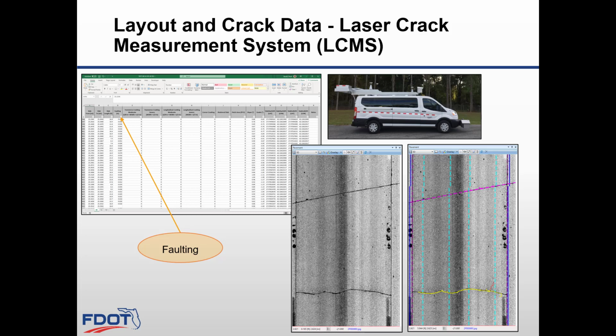This new technology provides an alternative method of collecting data for the distresses in the slabs, especially in more urbanized areas where the field reviews are more difficult and traffic congestion does not allow lane closures, to perform a detailed distress analysis measurement, especially for faulting. This technology measures faulting height. This will be covered in more detail later on under the new technology in Module 11.